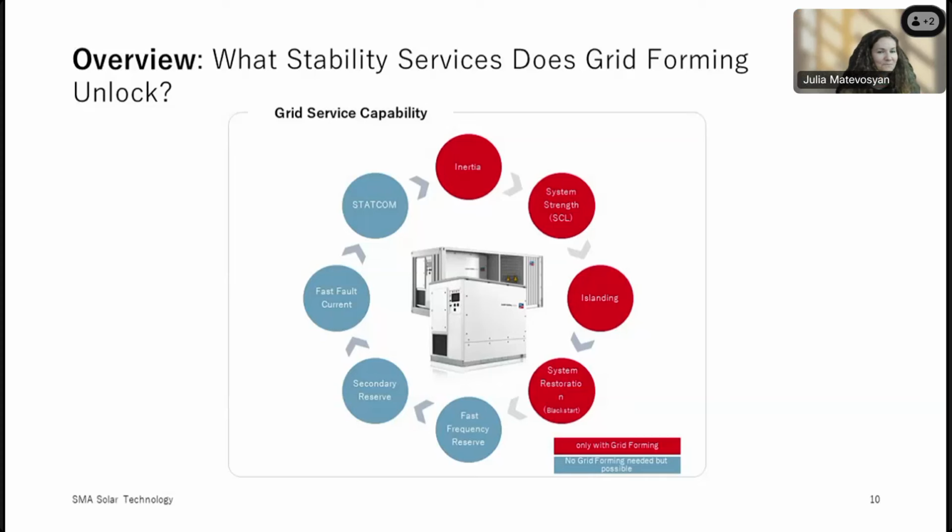The virtual impedance is needed in order to protect the inverter and to provide a steady state short circuit current into the fault. That's our way of doing that. There may be others doing it differently, but that's the SMA approach, which has worked over decades. Yeah, I mean, it's a current limiting device. You have to find some way to limit current.